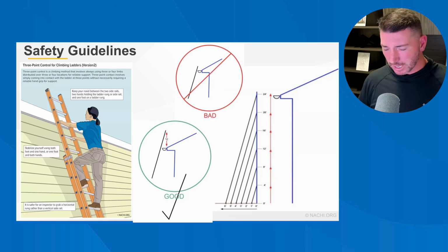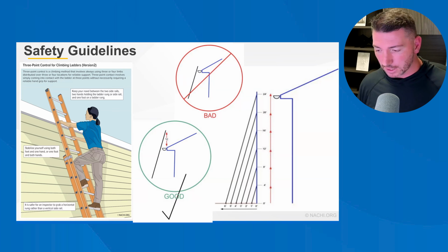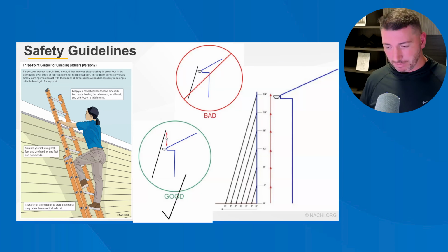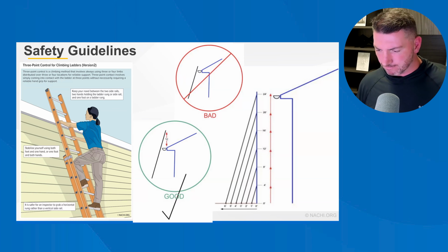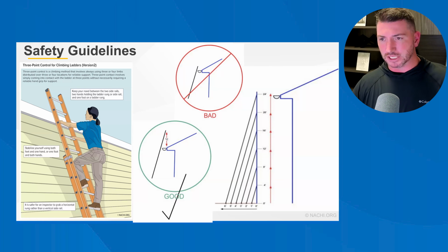And when it is 3 feet above that access point, you do kind of have to walk around it a little bit. So if you have to step around it, there should be a grab rail attached to the building to help you. I think that is only in the instance of a commercial building, but it's part of the notes. And again, while you're on the ladder, always face the ladder and consider anchoring the top of the ladder.